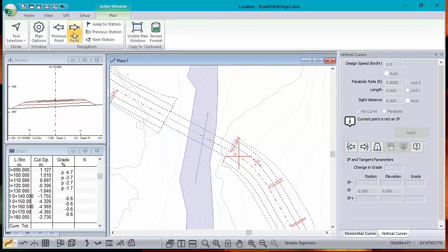Now watch how the left side works. We're down to minus 3.3 already. On the right, it's still 4.8. And as I continue along, before I get to the bridge, it's down to minus 2.2. And then when I'm on the bridge, well, that's the one just before the bridge, minus 2. And on the bridge, minus 2. Perfect, so they match. Now let's do the right-hand side.